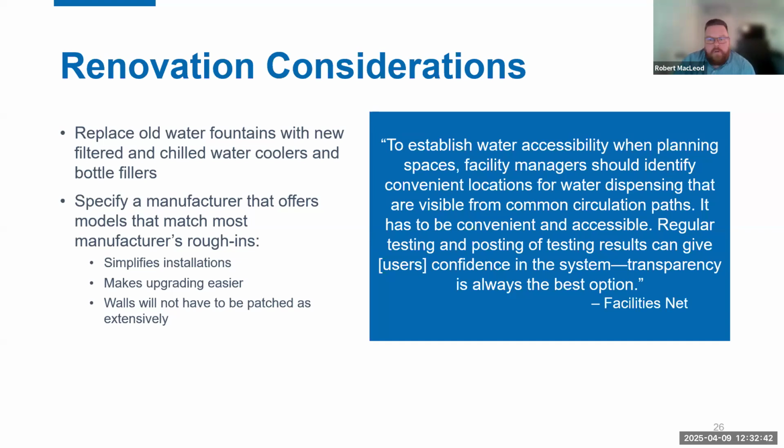When replacing the bottle filler or water cooler unit, specify a manufacturer that offers a model that matches most other manufacturers' rough-ins as well. So make sure that it's easy to replace them and also limit the amount of wall patchwork you may have to do, because you're using one that has a similar footprint to what may have already been there.